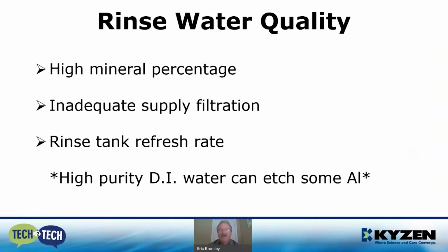The rinse tank refresh rate is something that should be considered, and this is more for batch cleaning processes, where you want to have a small amount of fresh incoming rinse water to make up the rinse tank constantly. You will lose some through drag out and evaporative loss, but it's a good idea to have a small amount that goes into the rinse tank, at a small rate, so it constantly refreshes itself.